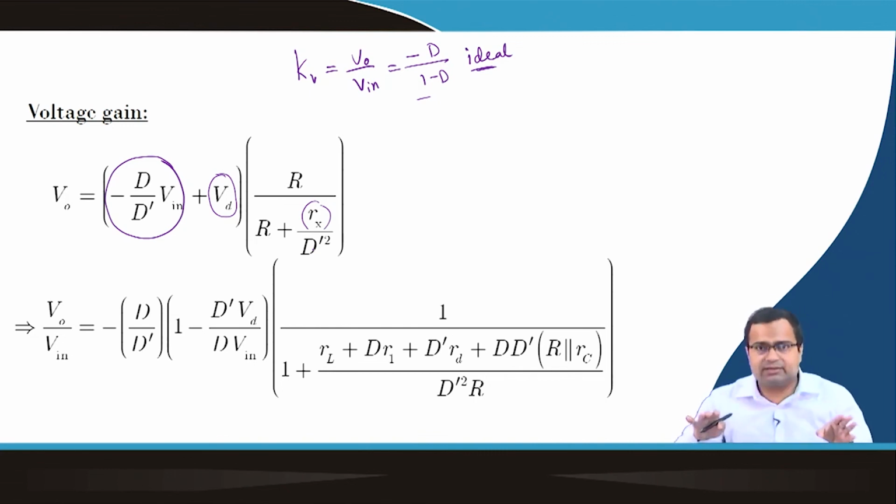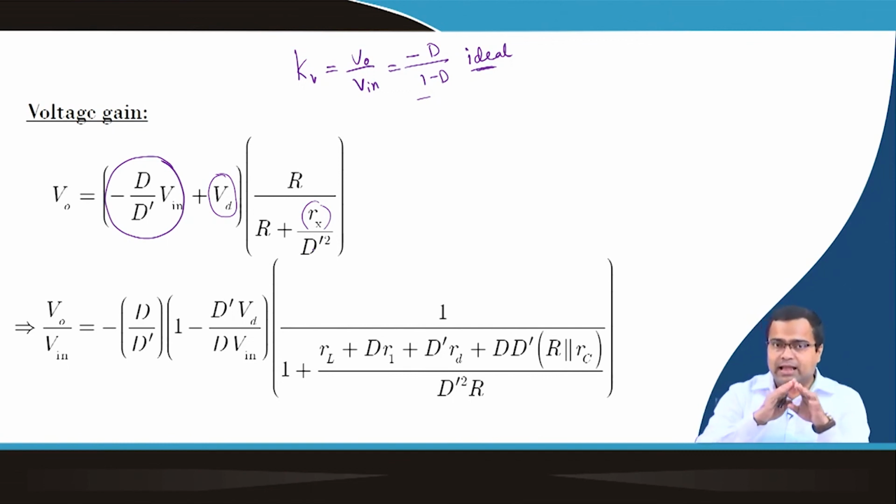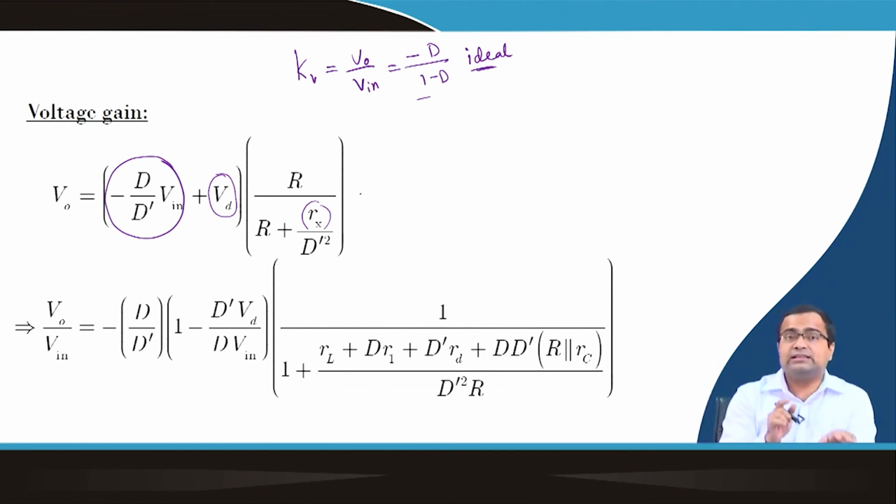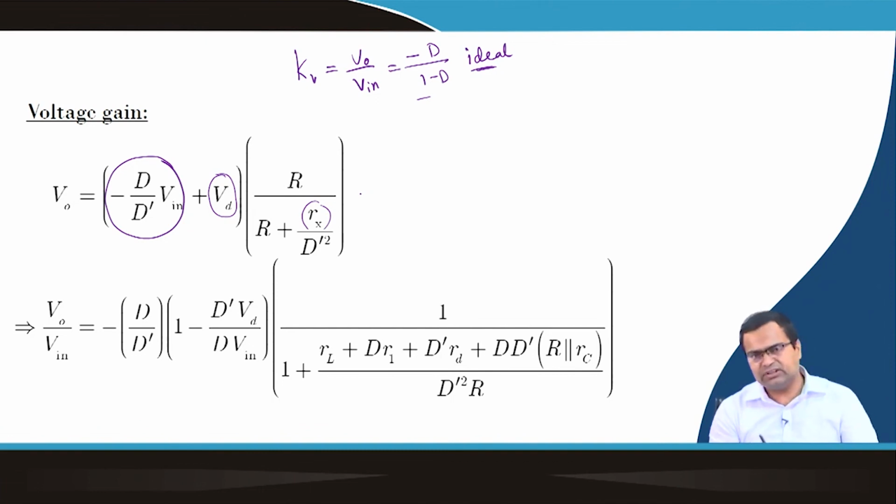We can simulate this buck-boost converter as well as the boost converter, and I suggest that you verify the average value of the inductor current and the output voltage for different load conditions. Using this analytical DC equivalent circuit, you can predict the practical voltage when you set a fixed duty ratio and vary the load current. You can predict using this analytical formula, and carry out the same thing by simulating. We can check whether we can predict it or not.